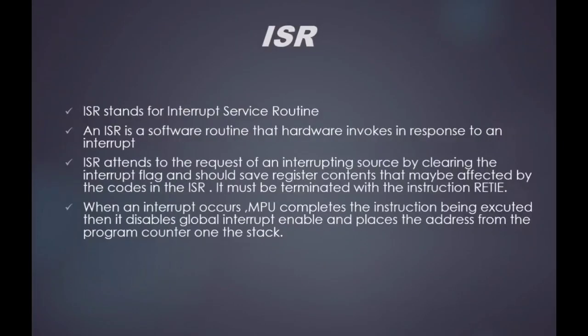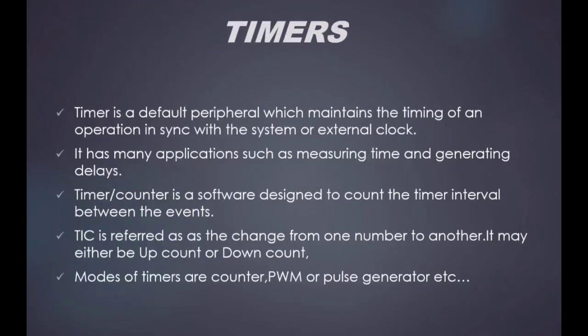ISR stands for Interrupt Service Routine. An ISR is a software routine that hardware invokes in response to an interrupt. The ISR examines an interrupt and determines how to handle it, executes the handling, and then returns a logical interrupt value. If no further handling is required, the ISR notifies the kernel.